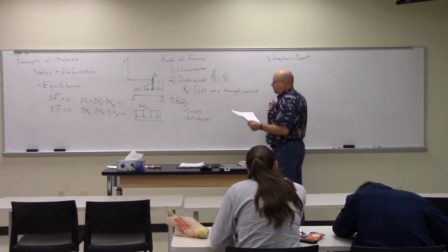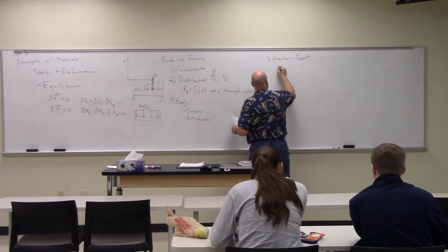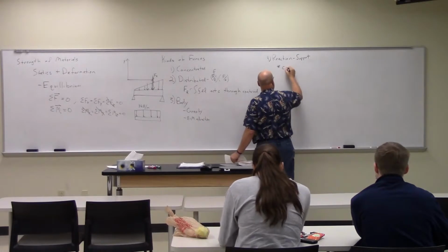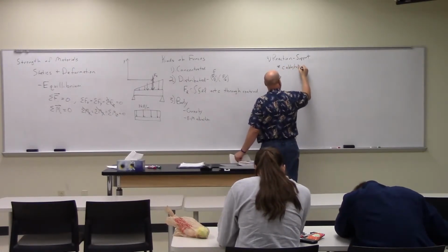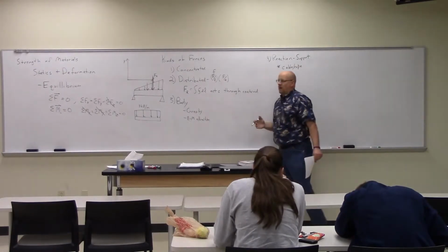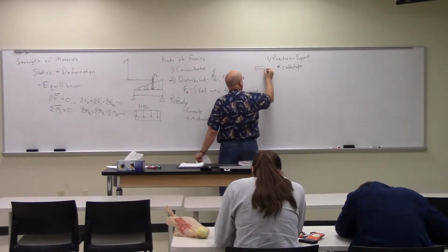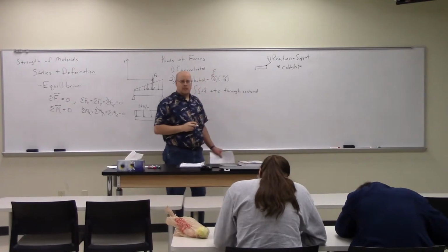So in 2 dimensions, which is where most of your statics work, there are several different kinds of reaction forces. Right? So there could be a cable or a rope attached to the end of the beam. So I've got my beam here, and I have a cable attached to the end.